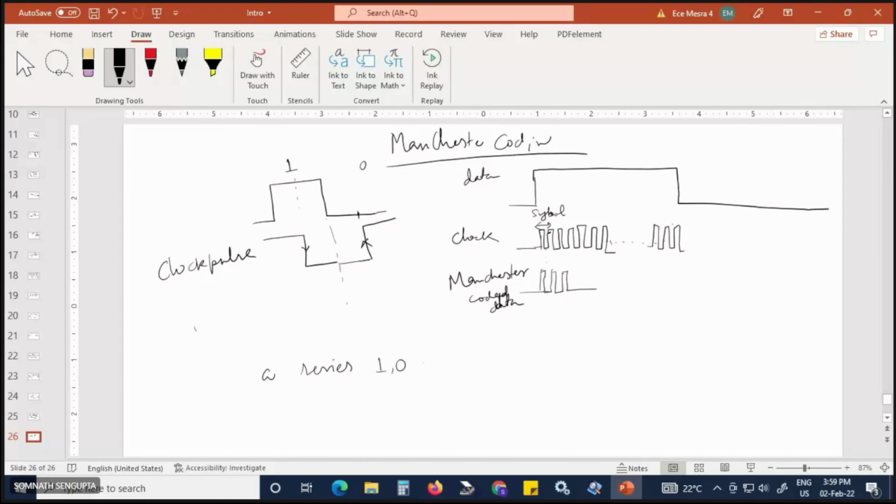Then if you trace it on a CRO, if they all remain the same, the rise time and fall time will occur at the same time. That means several times the same waveform is superimposed on the screen, and then it will look like an eye.